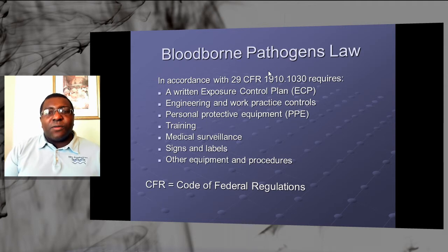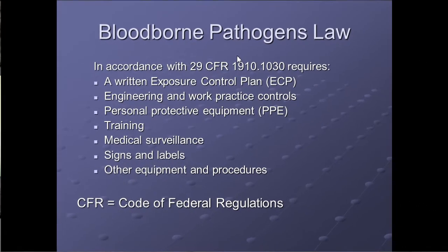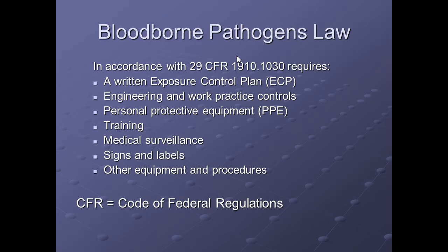You're going to want to use very strong gloves that are made puncture resistant, where you could grab a hold of the items in the pump and pull them out without getting yourself exposed to a needle stick.